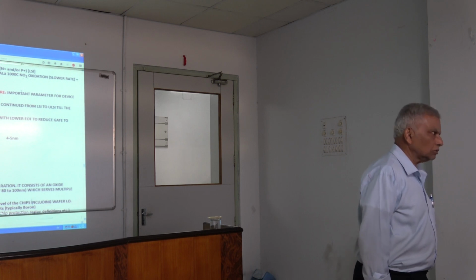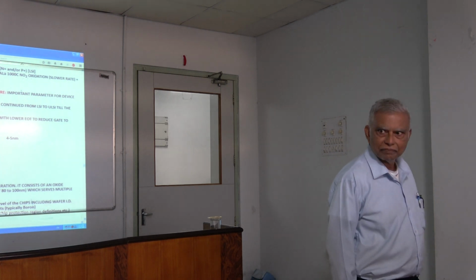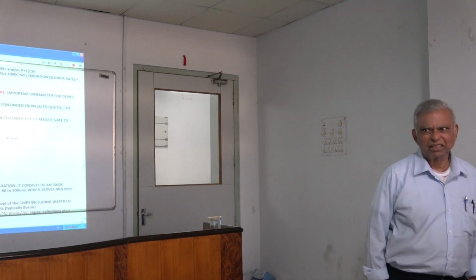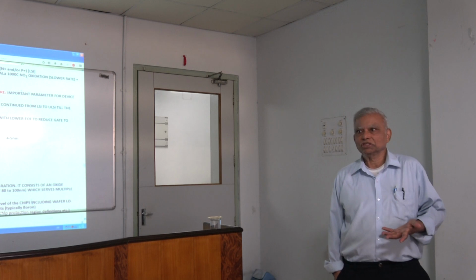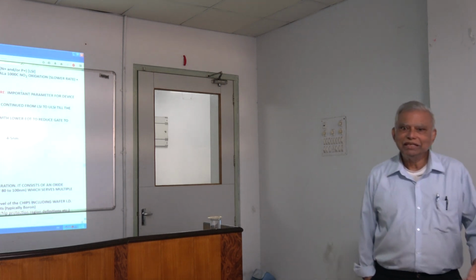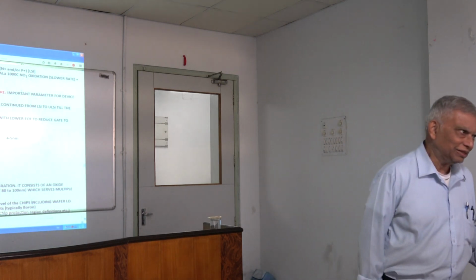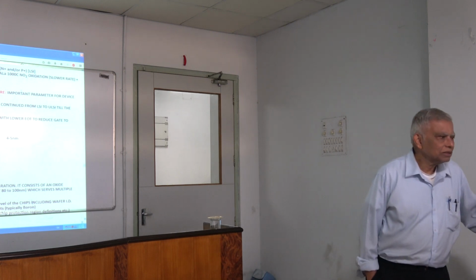What's the EOT? You know what EOT is? Whatever the dielectric is, what is the equivalent oxide thickness? Everybody measures in terms of that kind of parameter, such that the capacitance is the same had it been an oxide of that thickness. So that's what EOT means. That's all it means. It's a way of addressing thickness.